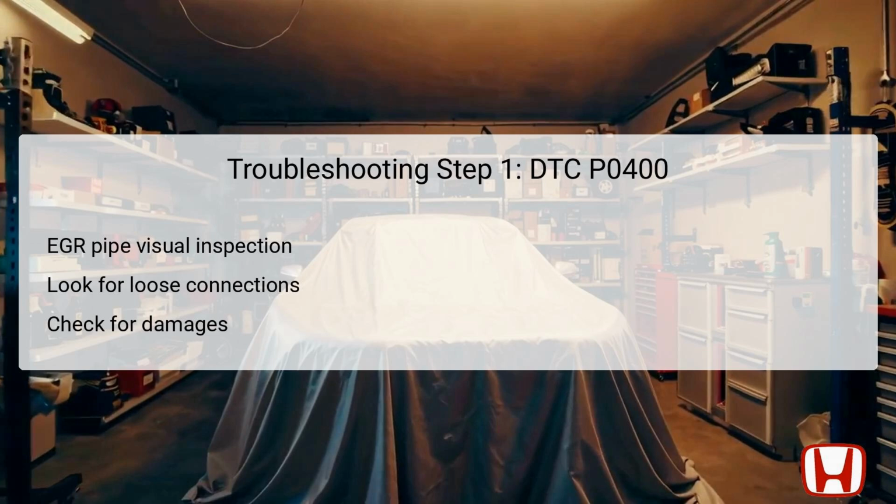In cases where damage is identified, the recommended action would be to either reconnect the loose sections or replace the damaged EGR pipe entirely. Completing this inspection accurately is crucial before moving forward, as it establishes whether there are underlying issues impacting EGR system performance.